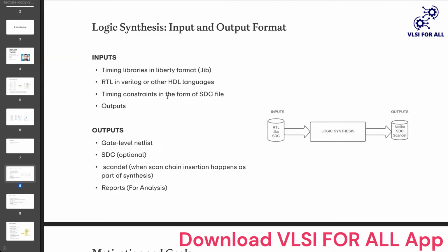As in, I define the throughput. From the time I get the input, it does the logical calculations and generates the output, I need all this to happen within, let's say, 2ns, just as an example. So that's a constraint. The throughput, or the latency, for that design should be 2ns.